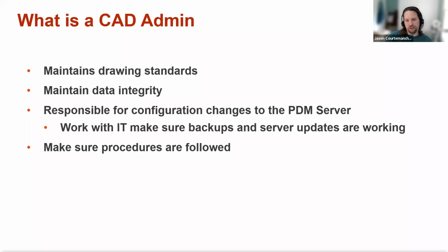But as you scale, or someone leaves and someone else takes over, one person manually makes the material library, then the next person comes and transitions the design to the content center library. And then before you know it, you have purchased parts that were made as an iAssembly or an iPart.